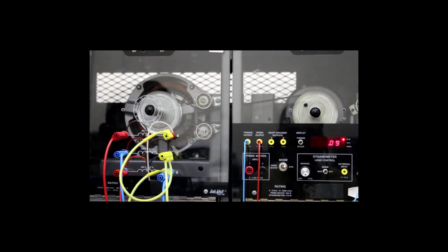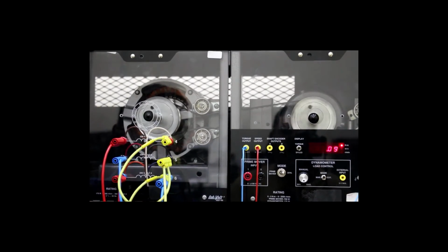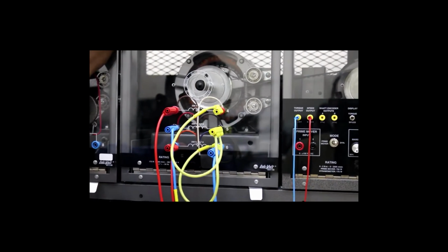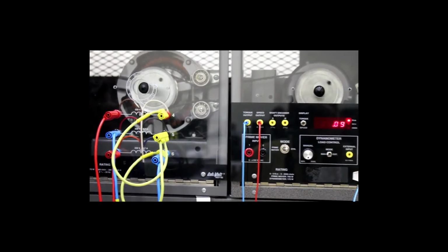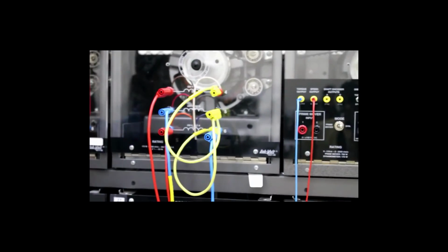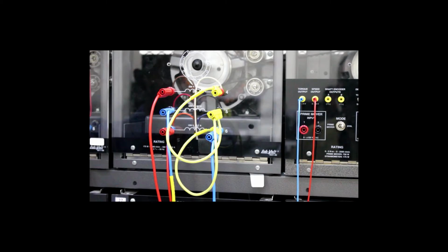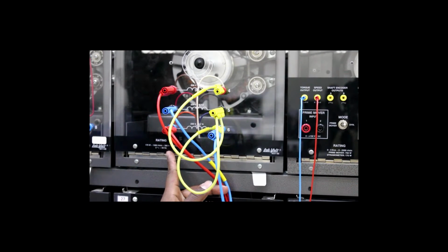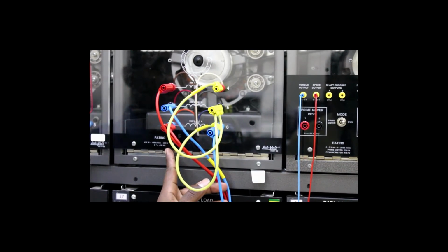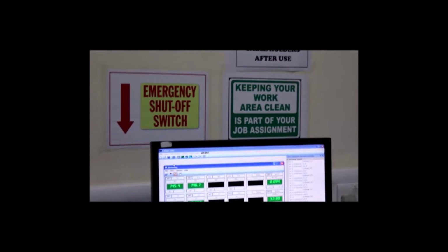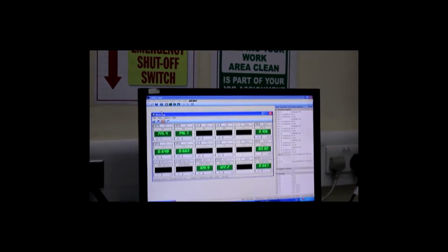Now the second requirement is to make the voltage the same as the voltage mentioned here on the module. Here it's 380 because we're working with a 220 volt system. There it is, 380 volts. So we're going to make the voltage measured by meter E1 380 volts. Let's go back to the metering. Now it's 145, and I make it 380.